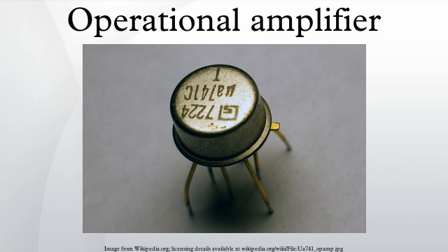Classification by internal compensation. Op-amps may suffer from high-frequency instability in some negative feedback circuits unless a small compensation capacitor modifies the phase and frequency responses. Op-amps with a built-in capacitor are termed compensated, or perhaps compensated for closed-loop gains down to 5. All others are considered uncompensated.